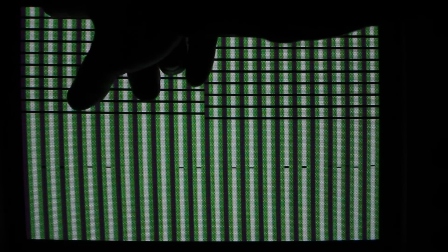So we're not actually changing these locations in video RAM. The locations I'm changing are actually up here in the left, and that's why you can see there's a little bit of a black block there. Up the top here, I first change these to red characters, and then down the bottom I change them back to black again. So by the time the electron beam gets around to here, it just has black in that location, and so that's what you see.